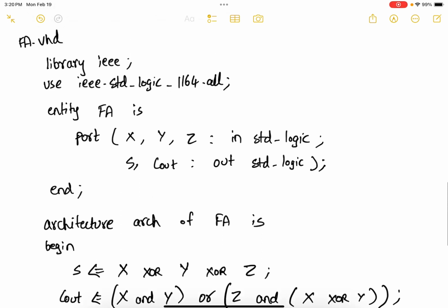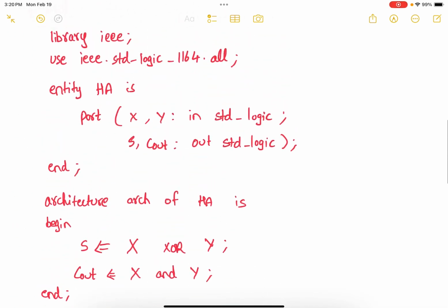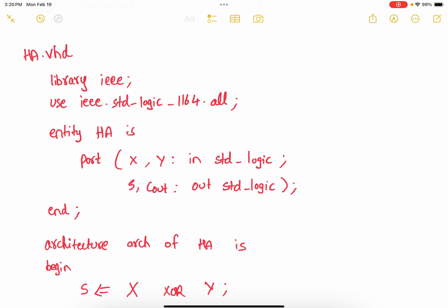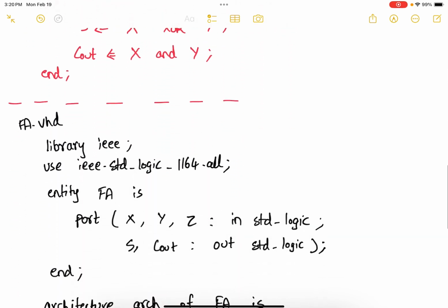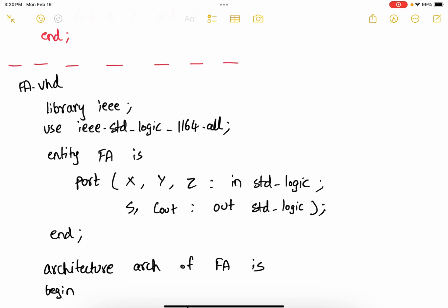So we first constructed the components, and what I want you to do is, once you finish writing the half-adder.vhd, make sure you thoroughly test it on ModelSim. Once you test that, write the full adder component, test that thoroughly on ModelSim to make sure that the equations are right. Once you're done with that, we can go with the main entity file.